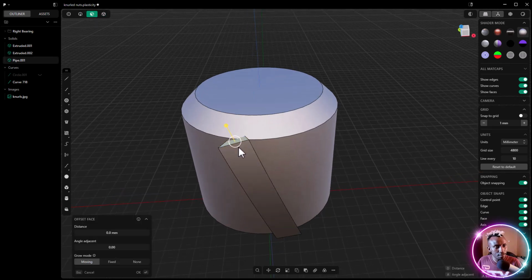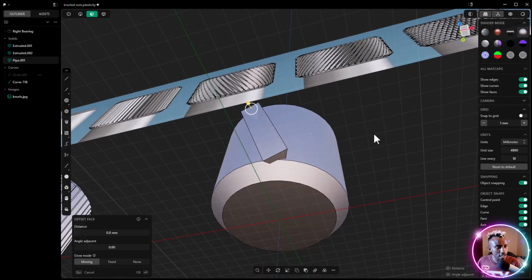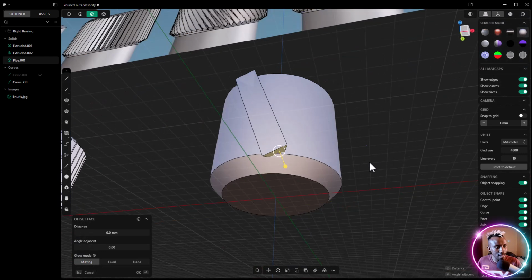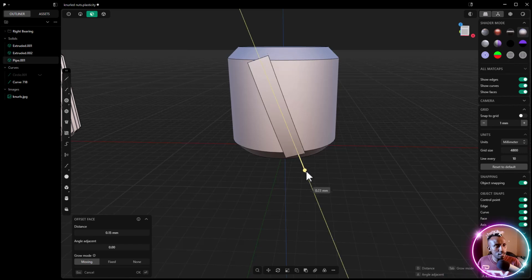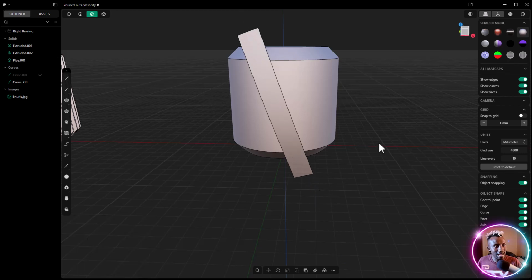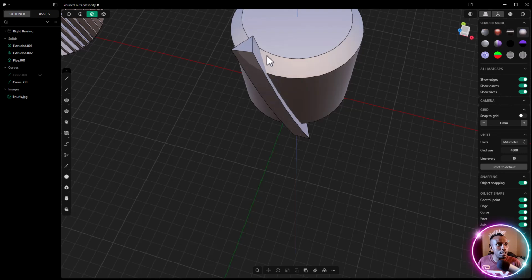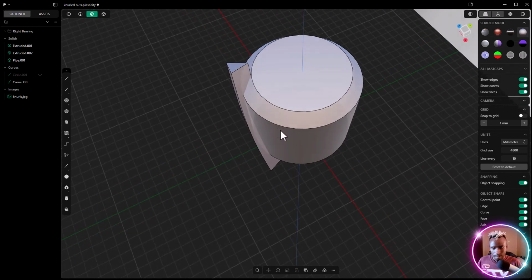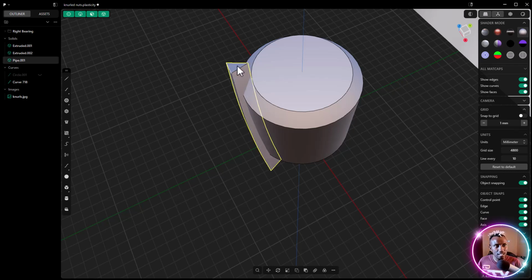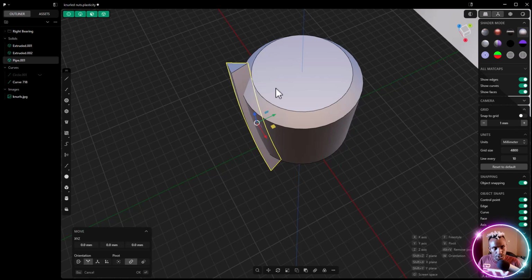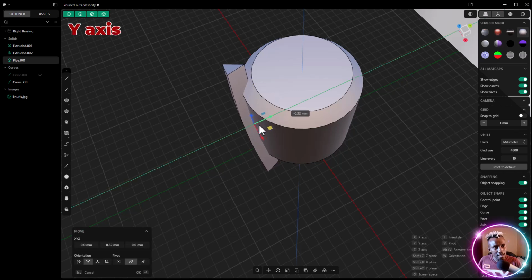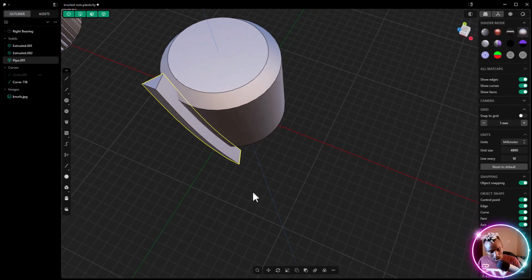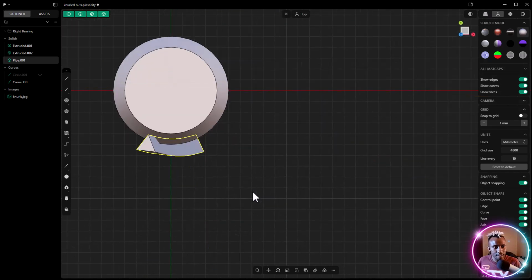want to select this face, rotate and hold down Shift to select this other face. And if I pull this, we're going to increase the height because I wanted it to go beyond that. Hit tab to activate all those, so to be able to select this as a solid. Then I'll hit G, then move it in the Z axis slightly outwards, maybe up to that spot. There we go. And now, as usual, let's go ahead and hit 7 on the numpad.